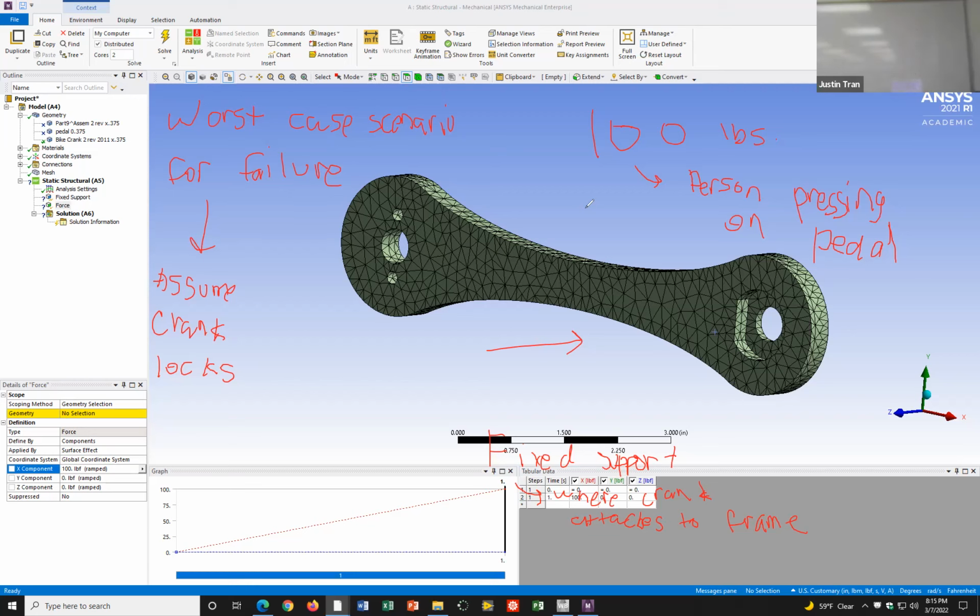What's their version of the pin support strategy? Pin support is the triangle, and the circle is a roller. When they do the solution now, they have no deformation in the Y direction, but it's free to rotate. Yes, a roller has that property too, so you can rotate around a roller too.